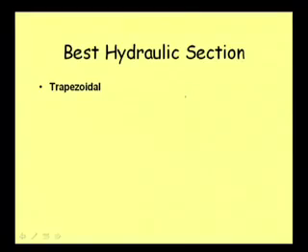Well, if we take a trapezoidal section of this sort, say the side slope is Z, and let us consider this to be symmetrical. Generally when it is man-made, we will try to make it symmetrical. Of course, in some cases in hills we may go for unsymmetrical also. If one side we have a slope and the other side we do not, then we may go for an unsymmetrical channel, but normally we try to go for a symmetrical section.